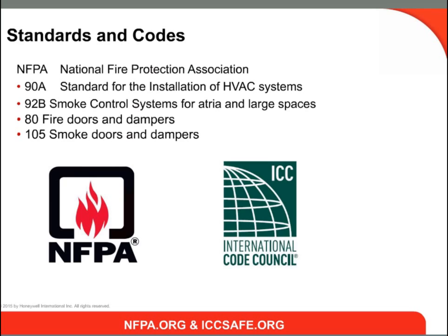Fire and smoke dampers must be installed in accordance with the manufacturer's instructions. Correct installation includes things such as providing adequate space to access them. There must be doors that allow access to the inside of the ductwork to inspect and maintain the damper. Also, the damper must be identified with letters that are at least 1/2 inch in height. After installation, they must be periodically tested and maintained to ensure that they will function in an emergency.